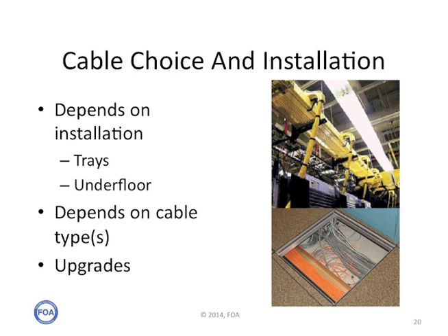It's hard to know where to start talking about cables and installation, as everyone has an opinion and every data center is different. Some data centers use cable trays above the racks, and others place cables under raised floors. In the racks, the cables are probably going to be distribution type cables, but under the floor they may be armored to protect against crush from other cables. Micro cables blown into ducts have been used, as have blown-in fibers.